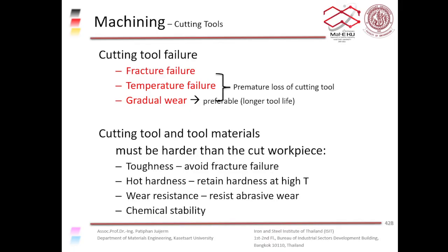The wearing causes the loss of tool shape and a reduction in cutting efficiency. Then you start to get more and more wear as the tool becomes heavily worn, and finally the tool will fail, similar to the temperature failure, with plastic deformation.